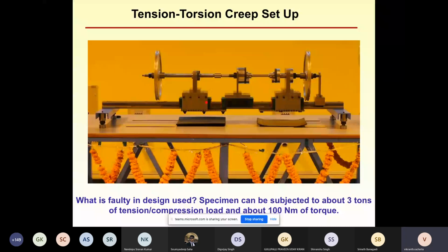So the ball nut is fixed and the ball screw is being rotated, and the ball screw shaft is attached to the inner raceway of a taper roller bearing. As I rotate this ball screw using the pulley, what kind of a motion will I generate for this particular column which is free to slide? It will translate along the rail. So I use this mechanism in order to cause translation of this column along the rail.